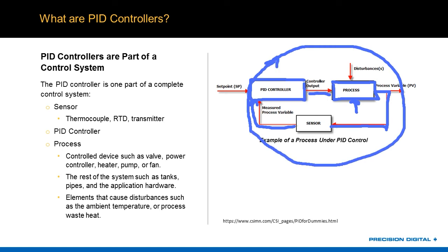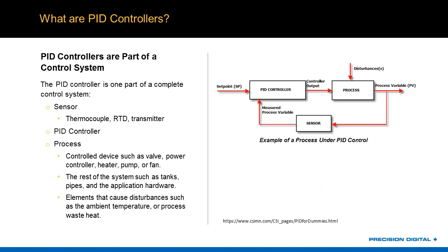Now, you could have, say, a dual loop controller that essentially is just this thing times 2. But that's a more complicated device. Most PID controllers you're going to run into are going to be single loop controllers. Provides an output to the system, which makes changes, which you measure, which you bring back into your controller. Boom, there's your single loop.